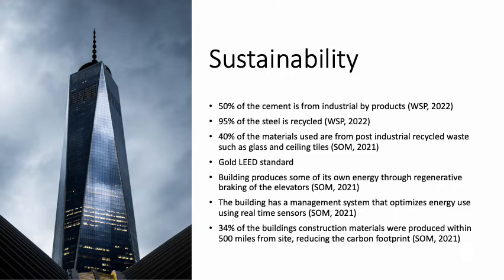50% of the cement is from industrial byproducts, and 95% of the steel is recycled. Now, it did achieve a gold LEED standard, the same as the Empire State Building. The building, as I've said, produces some of its own energy from the regenerative braking of the elevators. It also has a management system that optimizes energy use using real-time sensors. Now, that is slightly similar to that of the Empire State Building, but it is a little bit different as the Empire State Building was retrofitted for this purpose.